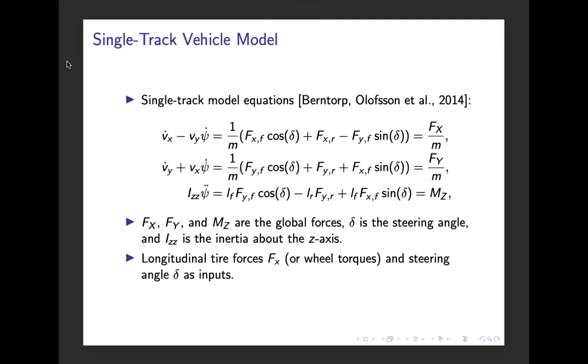Then we get differential algebraic equations that relate how the acceleration along the longitudinal x direction relates to, for example, the yaw rate and the forces that we apply on the wheels. Essentially we have the longitudinal, the lateral, and then the yaw direction. We can establish this based on the Newton-Euler approach and identify in which directions the forces and moments act.